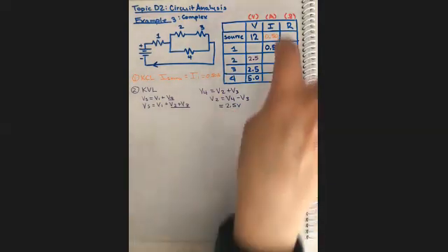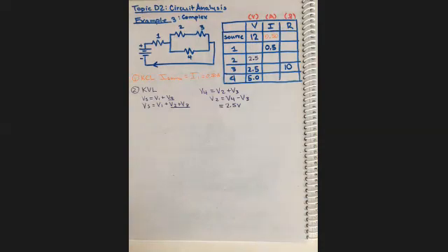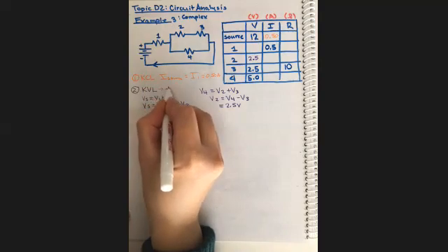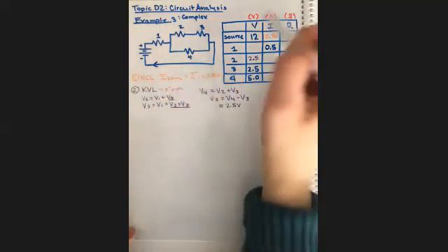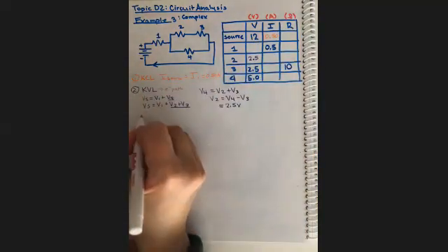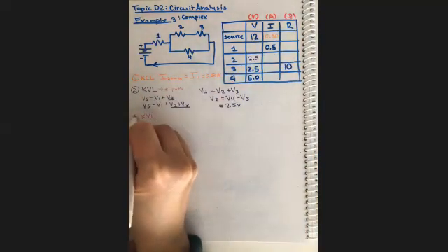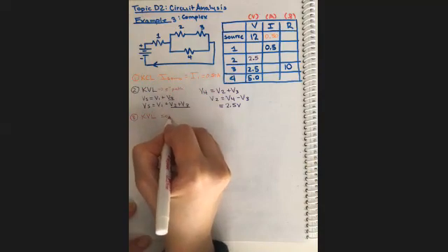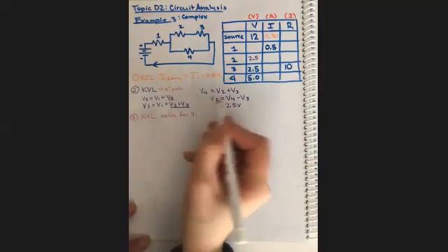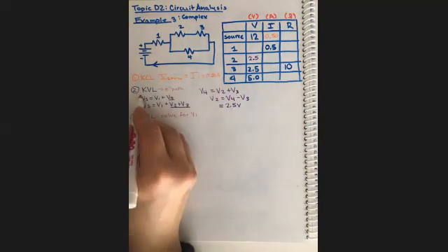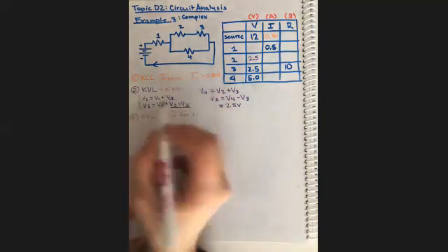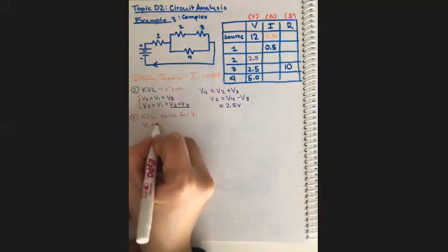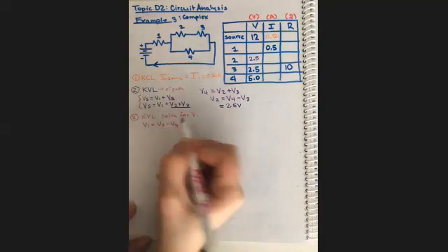Okay, so now we filled in 2. Pause this video to see if you can see any other places where we can move. You might say, well, we're already talking about KVL and looking at electron path. So why don't we just continue doing that to fill out the final V1? So we're going to use KVL to solve for V1. So if we go back to either of these statements, probably the first one is the simplest. We can do V1 equals Vs minus V4.